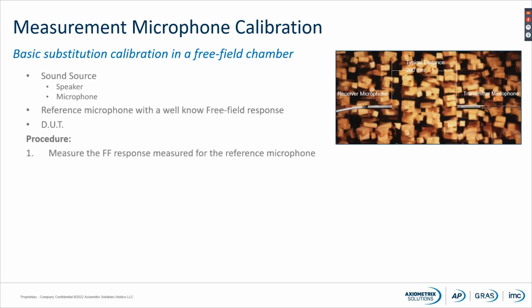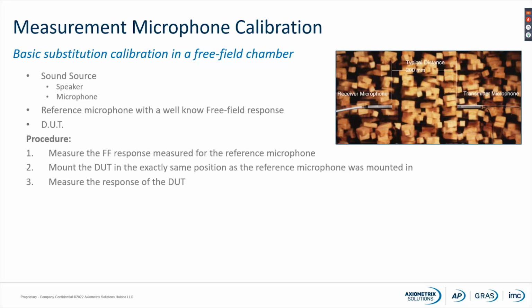The procedure is to measure the free field response for the reference microphone, mount the microphone under test in exactly the same position as the reference microphone was mounted in, and then measure the response of the DUT.